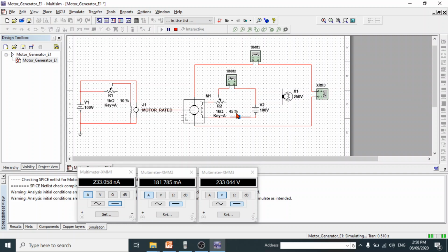To adjust the voltage, we need to adjust the excitation current, so the strength of magnetism. You need to click here and then find a value, until you have the voltage at the terminal of 200 volts. You can drag it down, and then the voltage reaches 205.083. So you can adjust further.